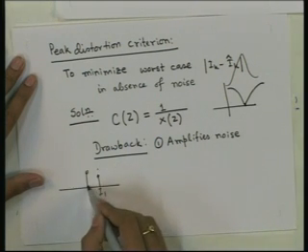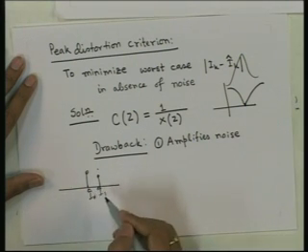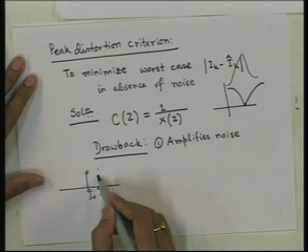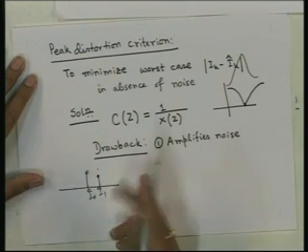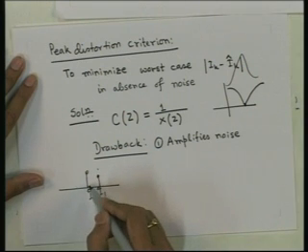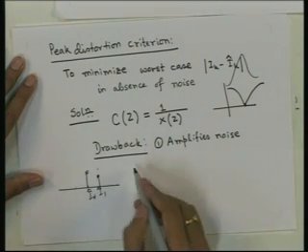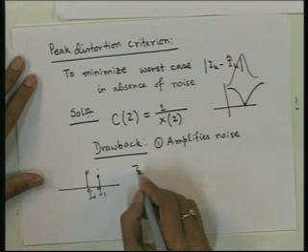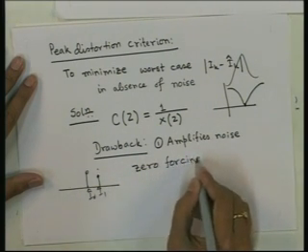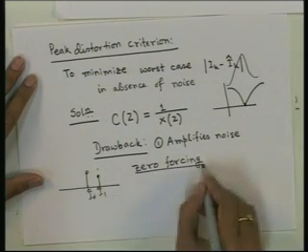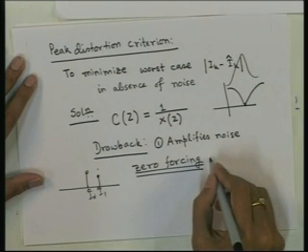There is no contribution of I naught in I 1 hat. So, if you estimate this I 1 hat, there is no contribution of I naught on I 1 hat and vice versa. So, there is zero interference from the neighboring symbols. This is referred to as zero forcing. So, that is why this equalizer is also sometimes referred to as the zero forcing equalizer,